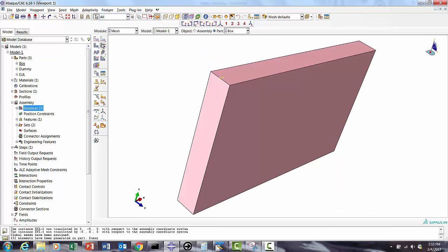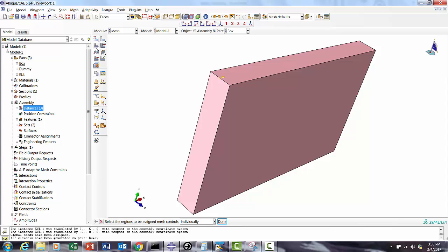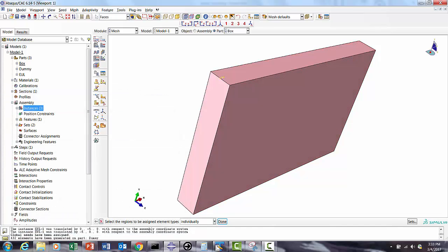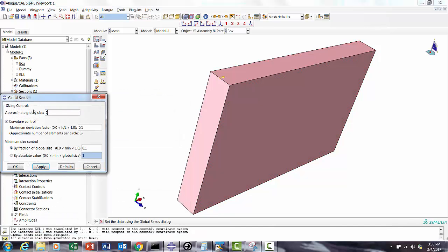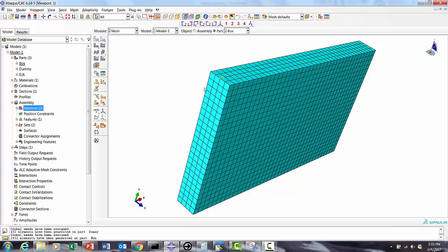But let's have a quick good structural mesh. For the box, we are going to put a bit fine mesh just for contact purposes, so that contact works very well. If you have a good fine mesh, then you also get quite good results. So we are going to put 2.5 just to get a good contact with the rigid box, and then we have the Eulerian mesh.